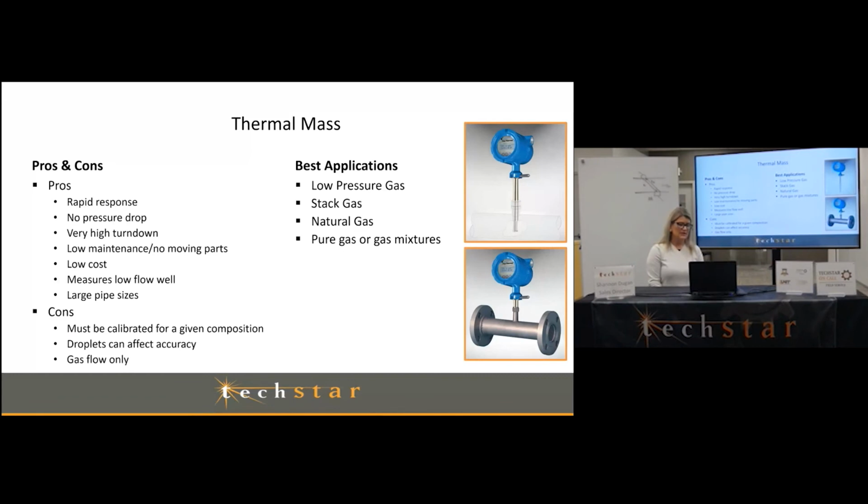Droplets can affect accuracy. So anything where you're having liquid droplets, it will cool the thermistors in there and give you an inaccurate reading. Really good for low pressure gas, stack gas, natural gas, any kind of pure gas. You can use them in some flare applications, mainly for some upstream type applications. Nothing that you would think of as widely varying compositions, because you have to stay kind of close to your composition here.